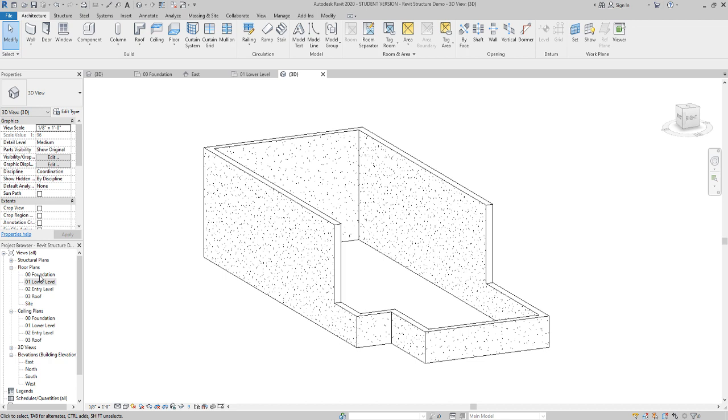We are going to be drawing the topography, and it also wants to create a camera view. The camera view is a little interesting because it'll create another 3D view for you. However, the 3D view that we're in right now is the one you should work in. The camera view that we create, we don't really revisit, but you can use it for a rendering later. So just don't confuse the new camera view that pops up with this one that has brackets.